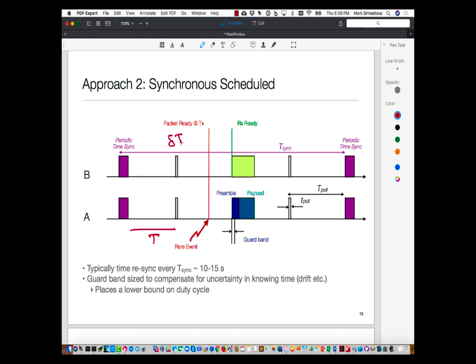So on this one, the transmitter takes into account the guard band, so it increases the time of the preamble sent down. There are many different ways you can orchestrate that. It could be the transmitter, or logically speaking the receiver. Either side can do it. But somehow, somewhere you have to account for it.